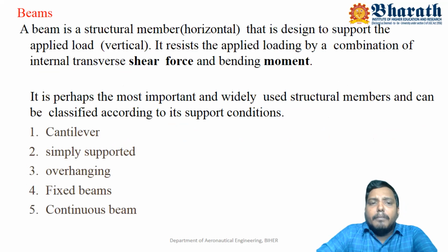Then what is meant by a beam? A beam is a structural member subject to transverse loading, which means the load is perpendicular to the beam axis. It resists the applied loading by a combination of internal shear force as well as bending moment. It is the most widely used structural member. It can be classified based on the support conditions.